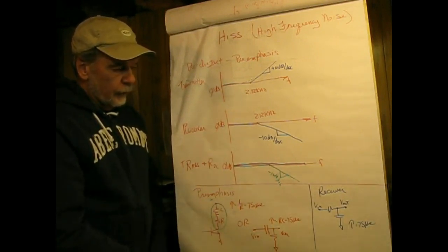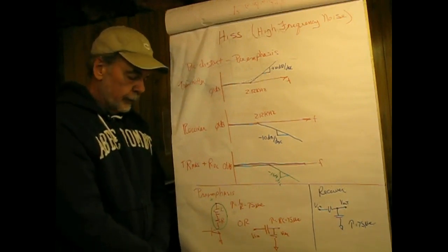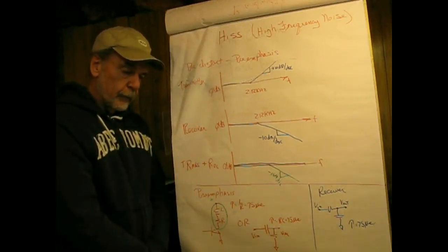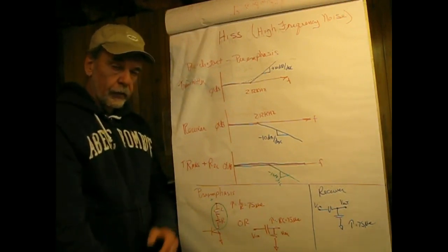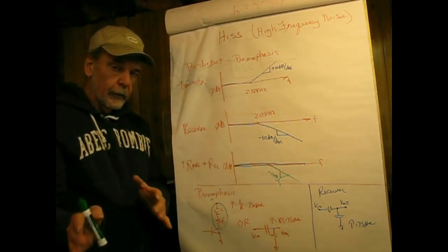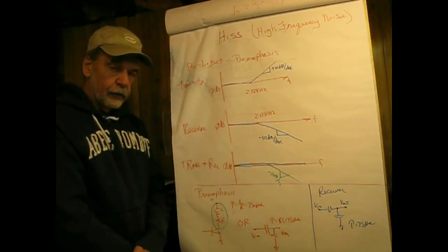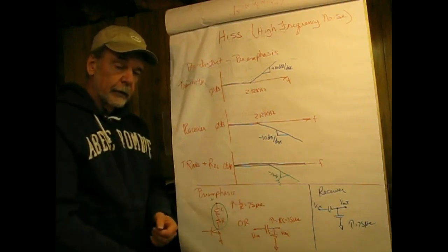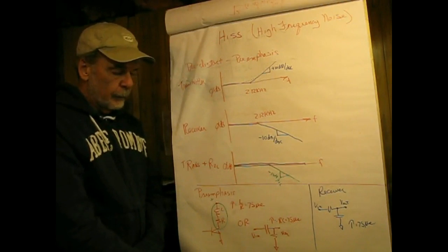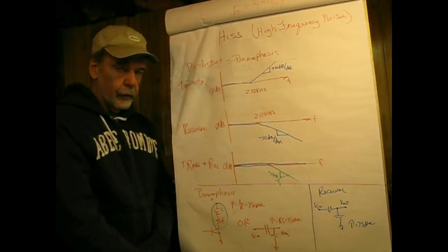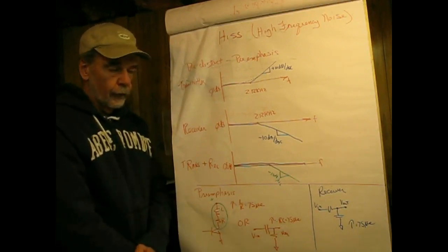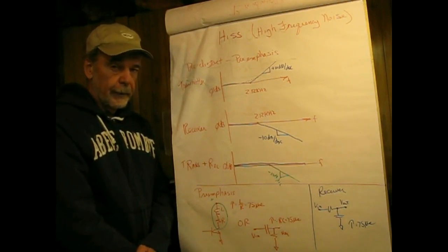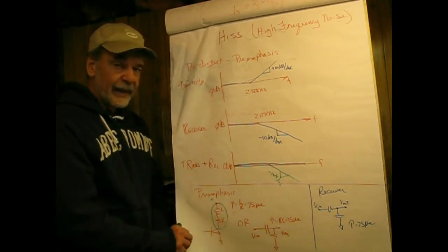Now we're not going to discuss stereo in detail when we talk about receivers, but in the early days of stereo in the 50s, people were directed to take an AM receiver and put it on the left side and an FM receiver on the right side. The broadcasters would feed the AM station with the left channel and the FM station with the right channel, and people could experience stereo, sort of. AM is limited in bandwidth, as you know, to 5 kilohertz. Further, the stereo image is very dependent upon the left and right signals arriving at the right time, and that probably didn't happen very well.